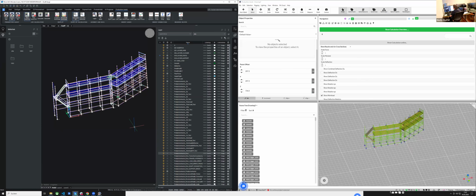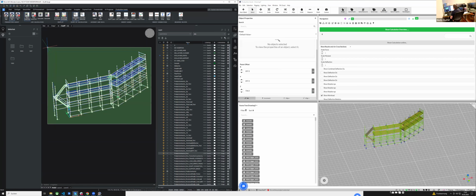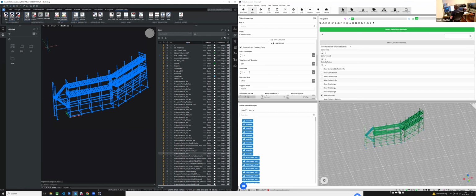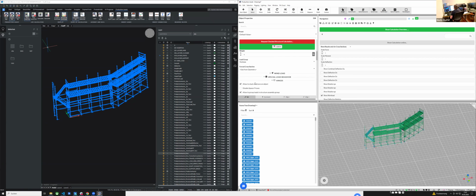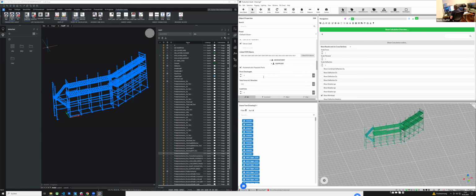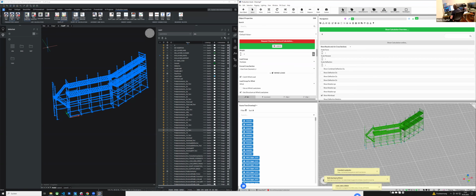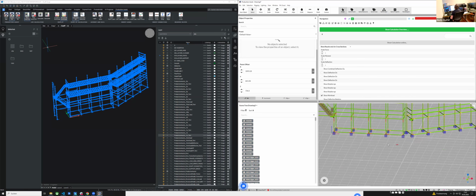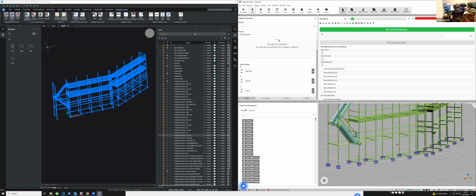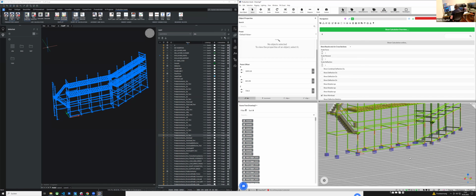So if you now go into here and select, for example, all the elements and tell them that these should get wind load, where we have it, structure, use structure as a wind load plane, this will automatically calculate the structure based on the wind load that these elements generate. You will see it becomes red, so it's overloaded in here. Well, there are no diagonals and nothing in there. So the diagonals are missing, so they would need to be entered so that this is actually acceptable.